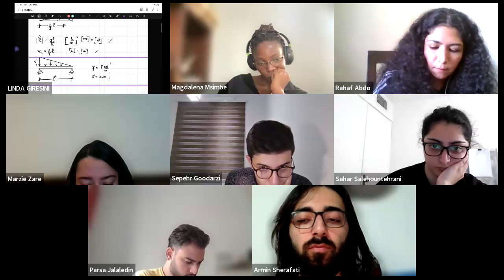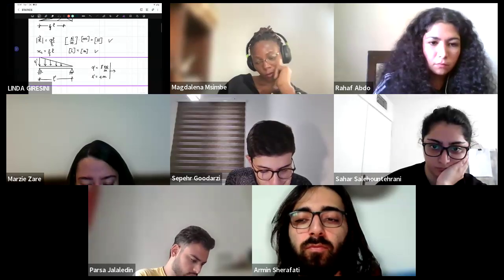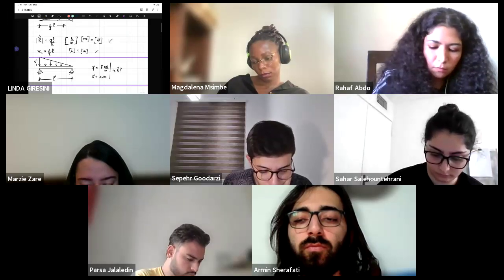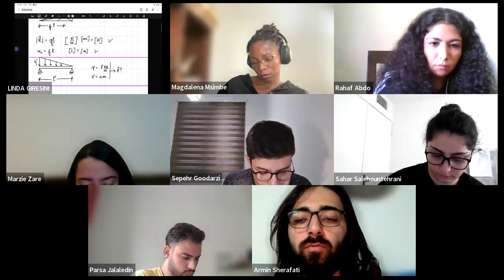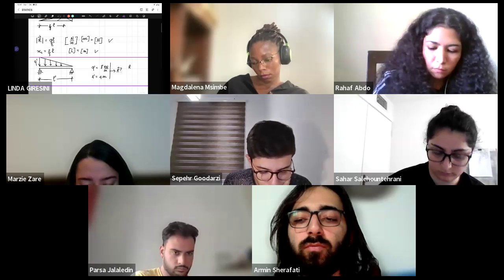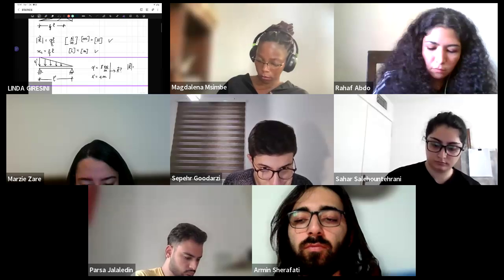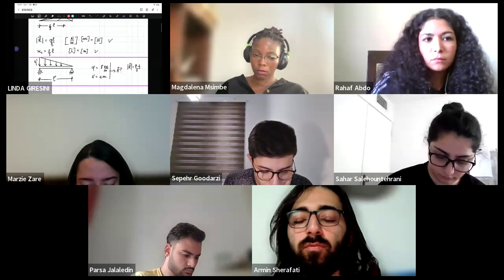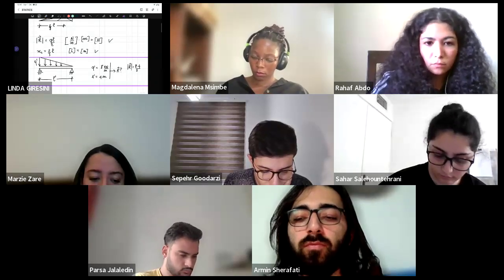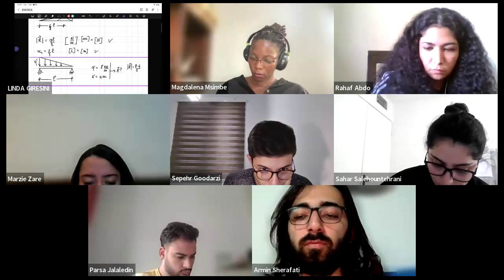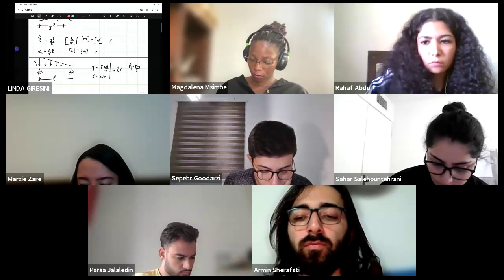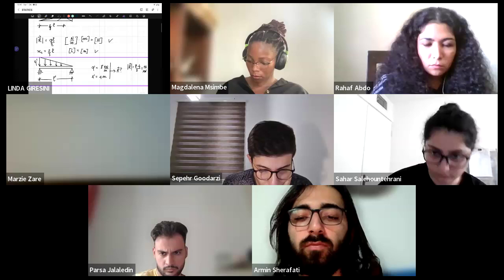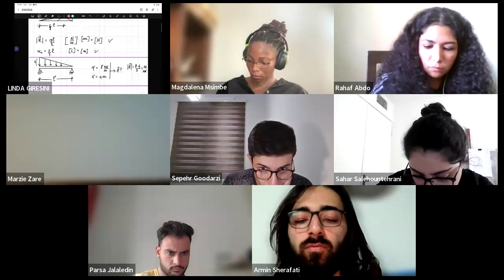Then you are asked to find the resultant. So I ask you, find the resultant of this force. The resultant will be QL divided by 2, so 8 times 4 divided by 2. 16, yes, thank you. 16 kilonewtons. Always put the unit, so kilonewtons.